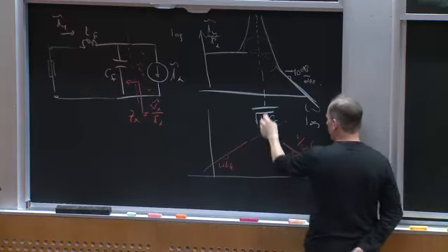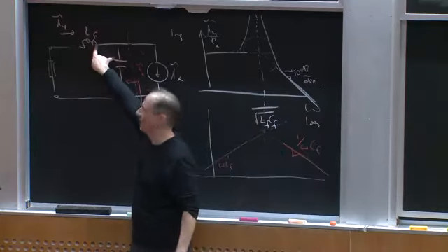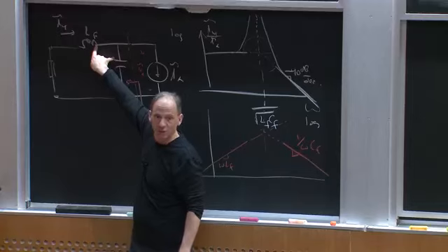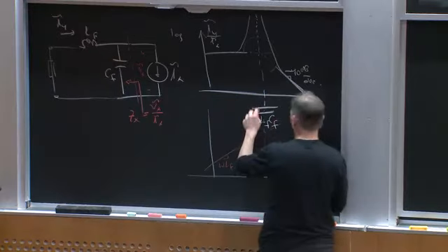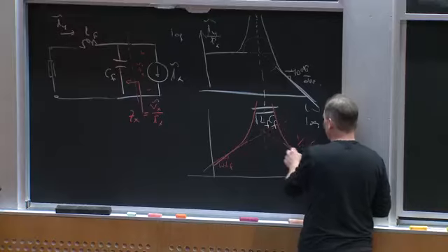And right at this cutoff frequency, these two are in parallel, and they are resonating against each other. One has a positive admittance, the other has a negative admittance, and they cancel. And this impedance would go off to infinity. So you're looking sort of back into an open circuit.